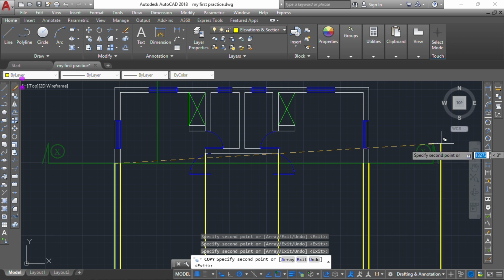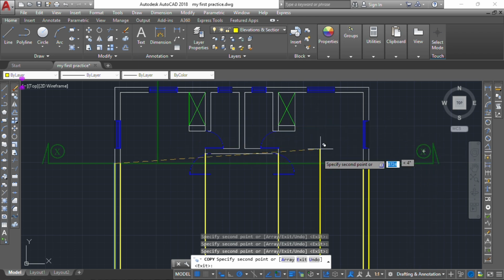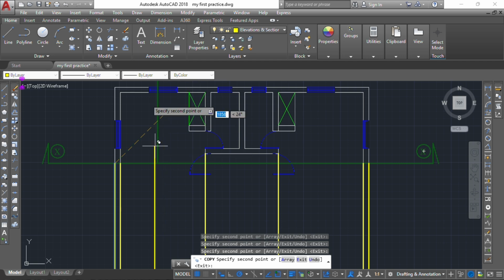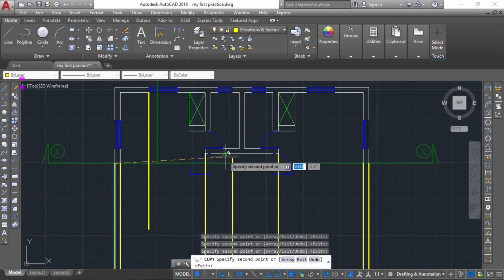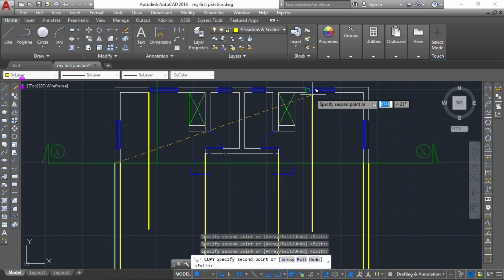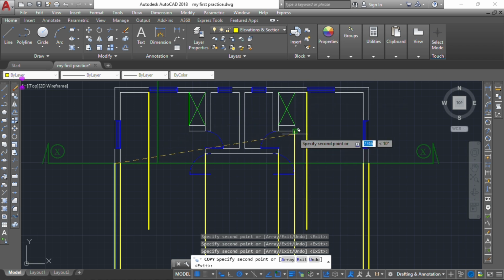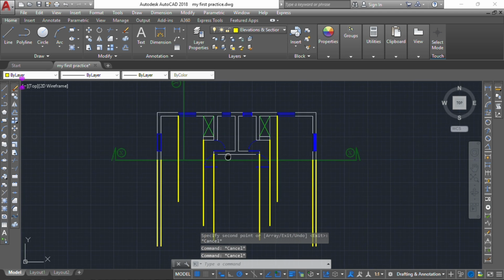And the direction of our arrow, our XX arrow, is indicating that we draw anything we are seeing across the cut plane, across the plane which we cut. So we are looking at it from this side, we are seeing this window also. Here we are seeing a plain wall, so we are not able to see these windows. And we are also seeing this window also. And take note, we are seeing the edge of this closet here also and here. I think those are all we are seeing.